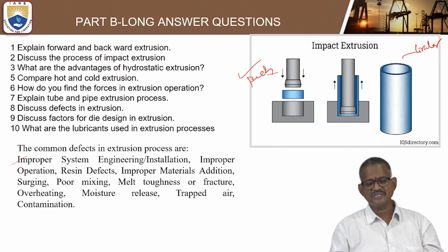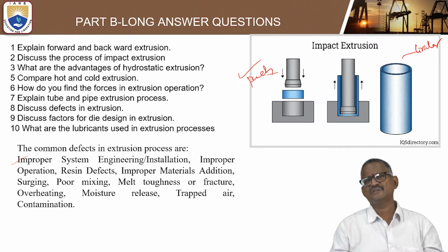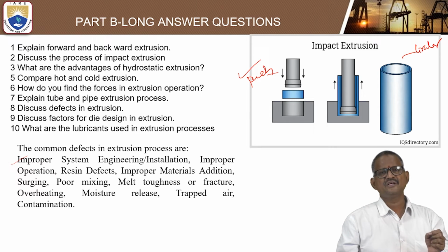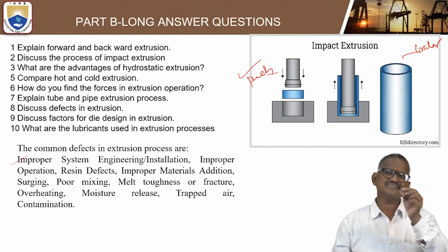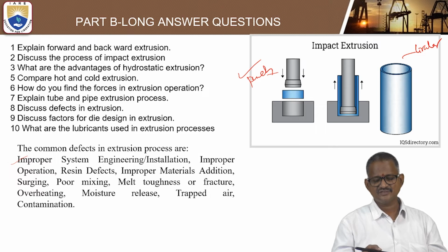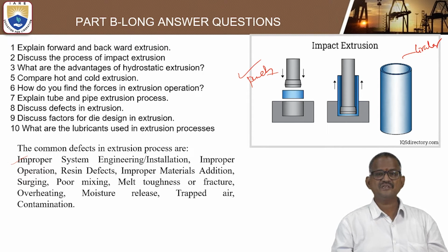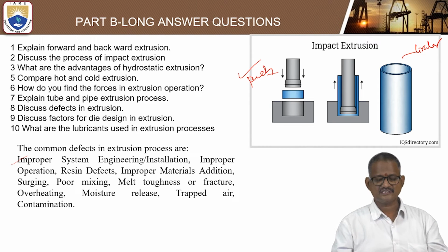And improper material addition. When changing from material to material, some purging should be done. Otherwise, if you first use LDPE material and the next time you use nylon material, it will get stuck inside the nozzle. That is why good purging should be done, so that nothing sticks in the mold, etc.